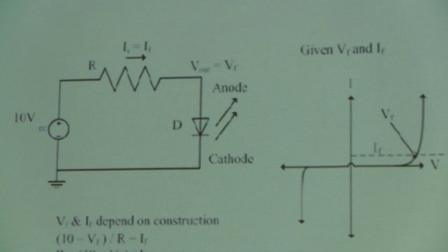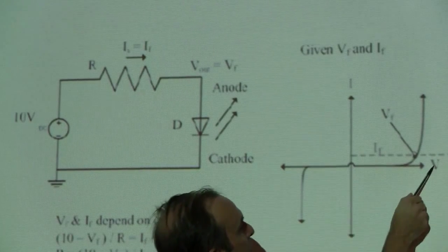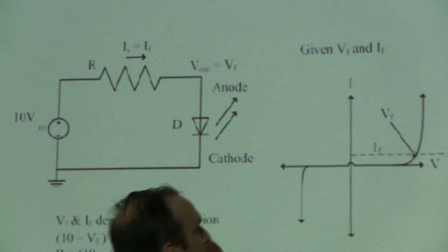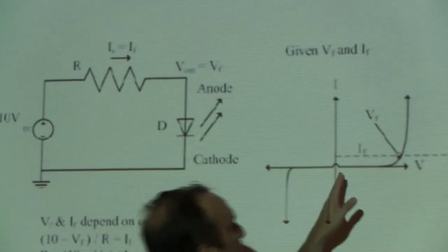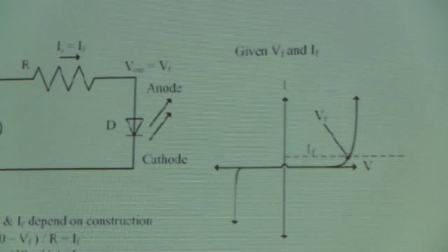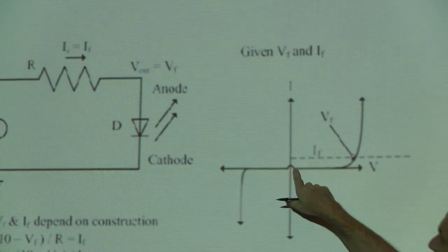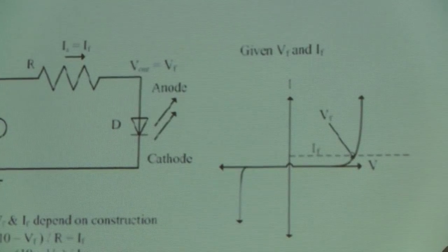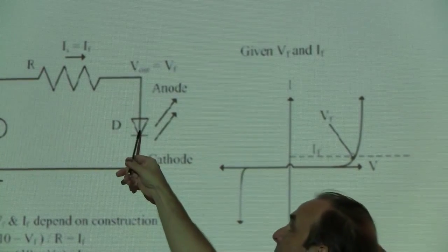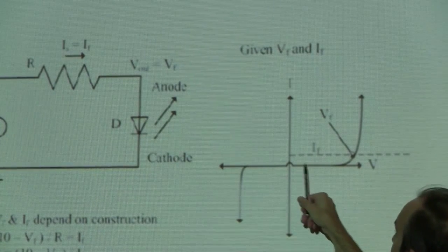But the way a diode works is there's something called an IV curve. This is current as a function of voltage. This is the fundamental relationship that explains all diodes, including LEDs. The way this works is if I apply a potential difference across the diode of just a very small amount, I'm here on the curve, nothing happens. Because I haven't given enough force to have current jump across the barrier or the gap between the positive material and the negative material. So I'm just cruising right here.